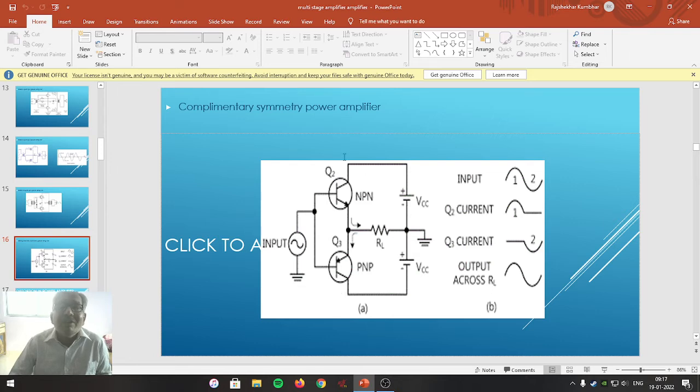But do remember, transistor Q2 is NPN and it is now getting the positive half cycle. So the base is of P type and it is receiving the positive half cycle of the input signal. So that's why the forward biasing of the emitter base junction is increased.